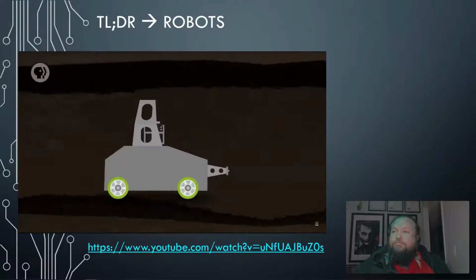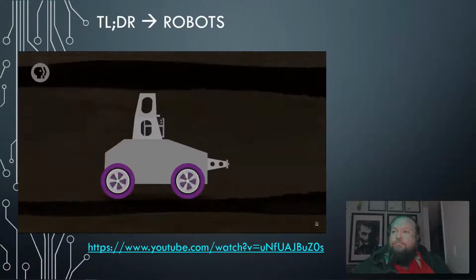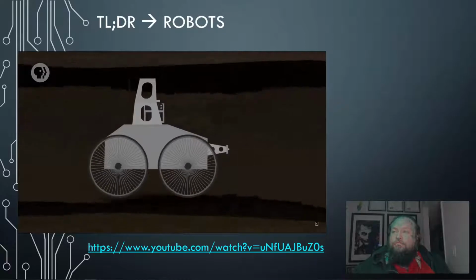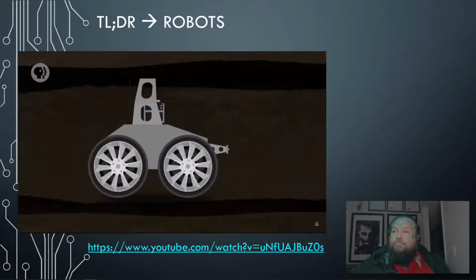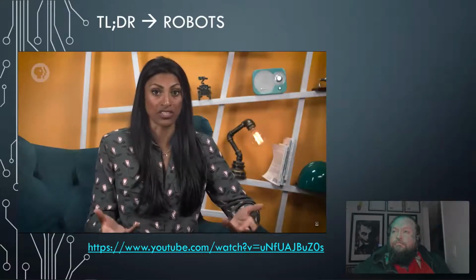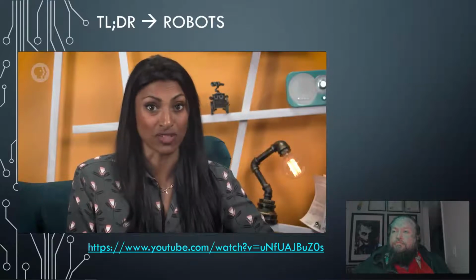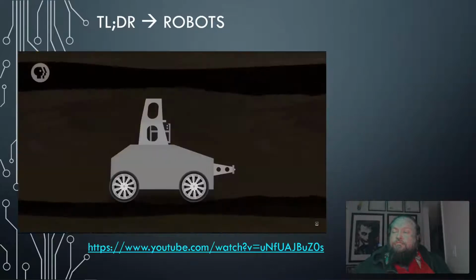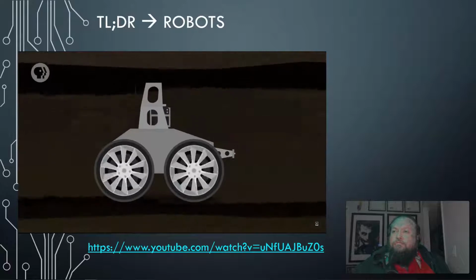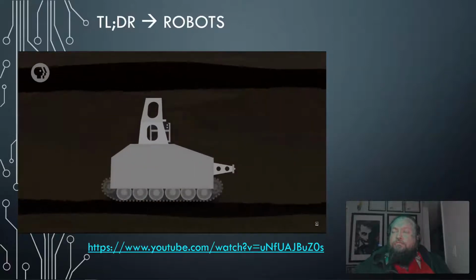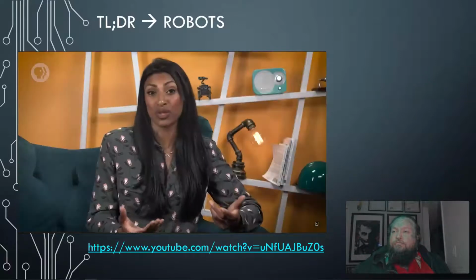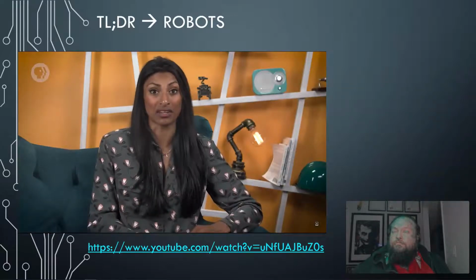Let's start with how it moves, a fairly basic requirement for lots of robots. Like with the mining robot, you could simply put some standard axles with wheels on the bottom of your robot and attach them to a motor, like on a car. That would be fine if the robot was going to be operating mostly on smooth, even surfaces like roads or factory floors. But most fruits are grown outdoors, sometimes in rough terrain and difficult environments. So you might need to design adjustable wheels that change height independently or add treads to overcome small bumps, like on a tank.